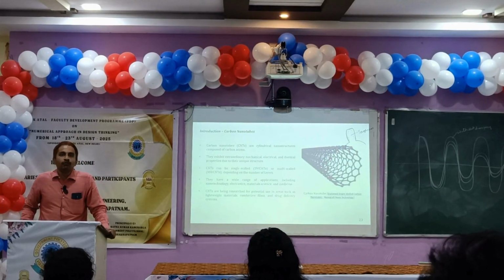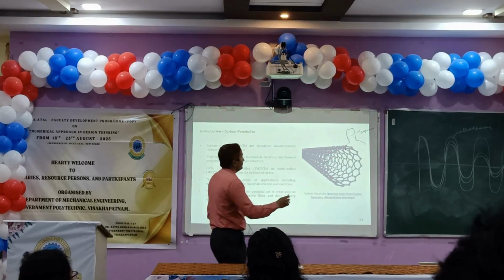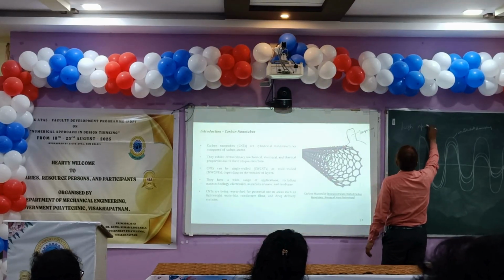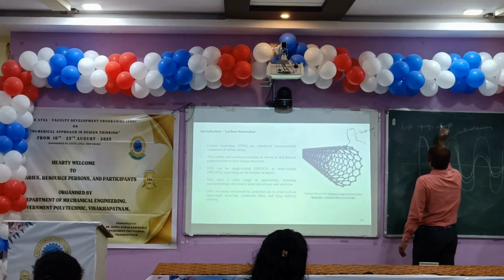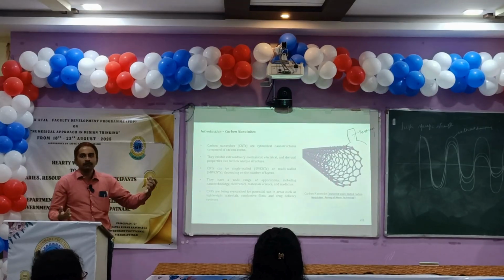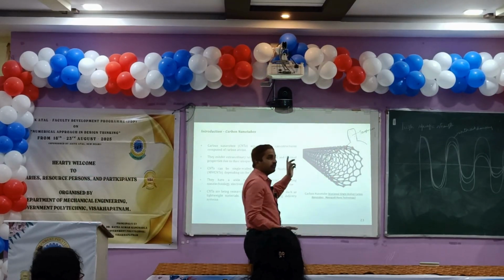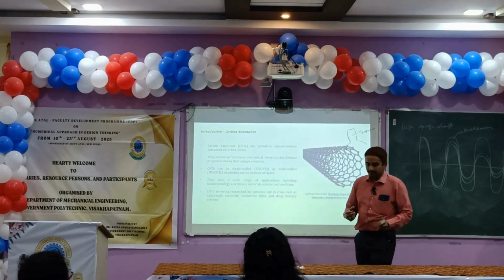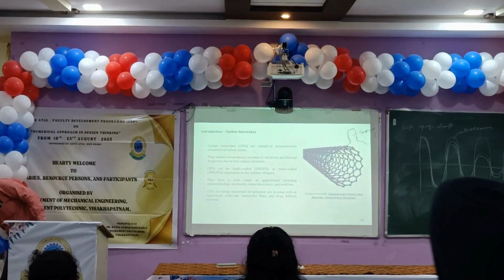So we go for composite structures because composite structures have high specific strength. High specific strength means without increasing much weight, you can get a similar amount of strength. So that's why we go for composite structures. As you have seen, I worked on sandwich structure. Why I worked on sandwich structures is that sandwich structures have got better ability to withstand loads in comparison to composite structures. So I will tell you an example of it.